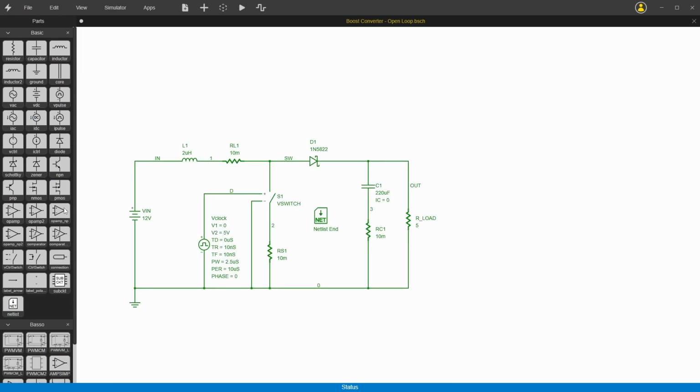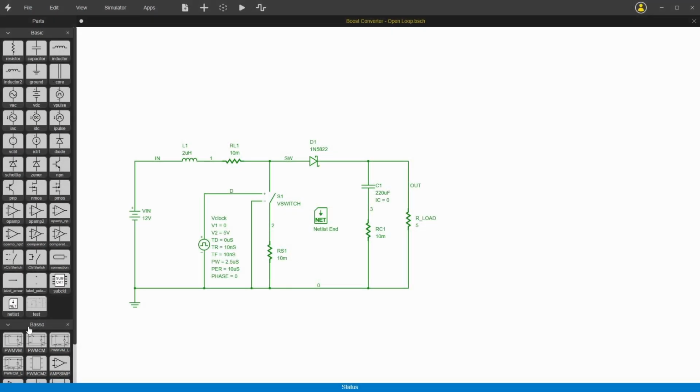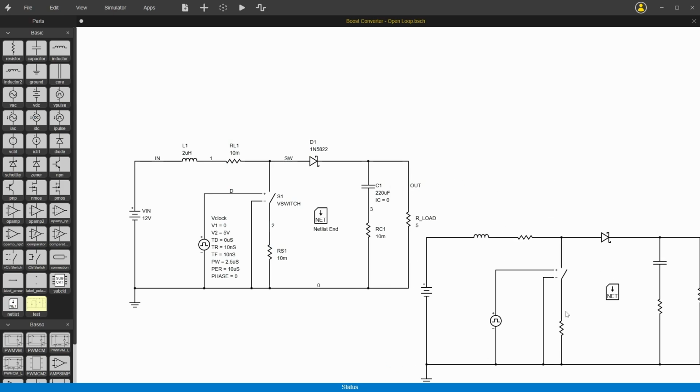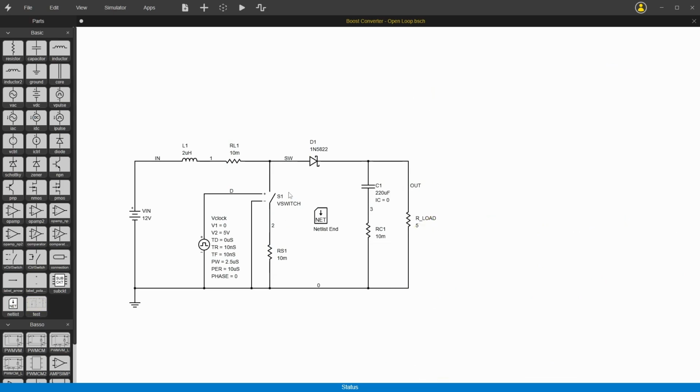To make a part now, any part can be a single part or it can be a schematic part. And if you right click on a library with a selection, you can say From Selection. I'm just going to put Test, and that creates a new schematic part here. And you can click on that, you can place the whole thing.